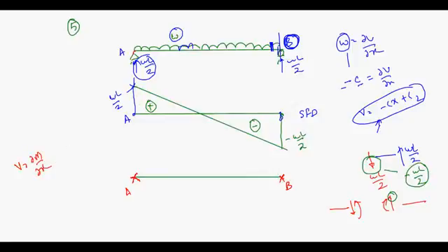Your shear force is positive slope and reducing slope. So you obviously know your V is linear, isn't it? It is C1x plus C2 is equal to dM/dx. So your moment will follow an x square relationship, C1x square plus C2x plus C3. X square is parabolic, so it is going to follow a parabolic relation.